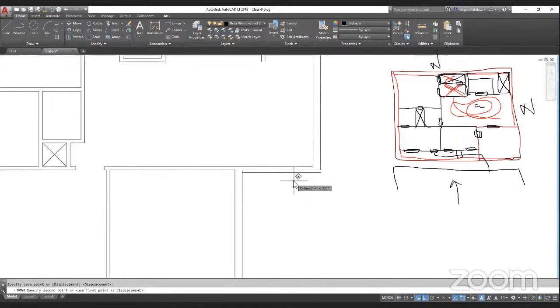Again, I'll move it 4.5 inches and it will become a 9-inch wall. And then trimming, TR enter enter, holding the shift button, I'm extending this line. That's it. Okay, then let me extend these lines. I'm using the trim command only and I'm extending these lines.